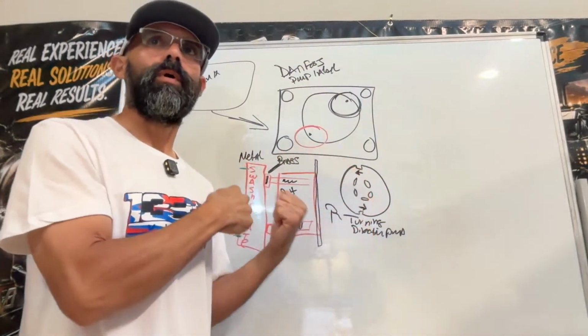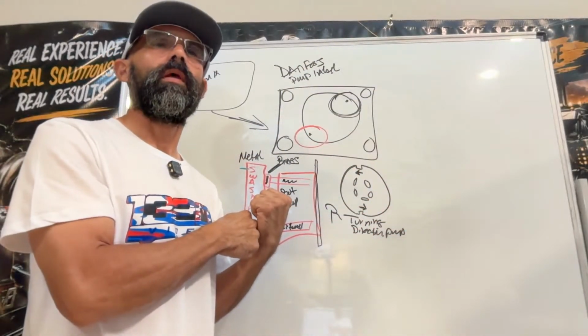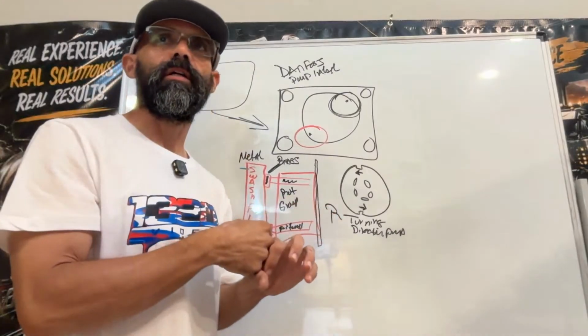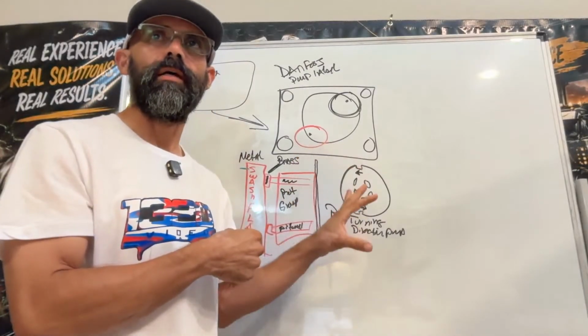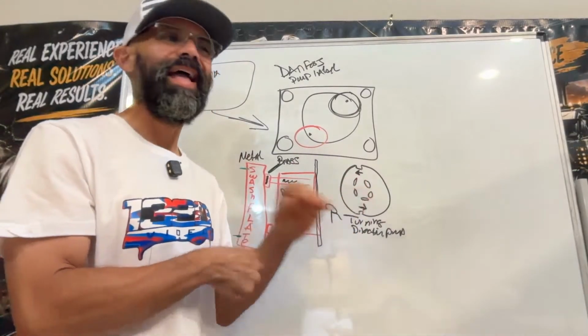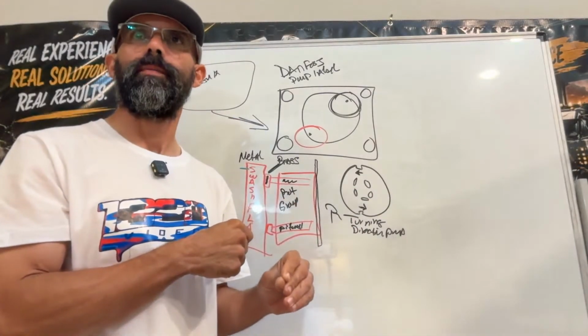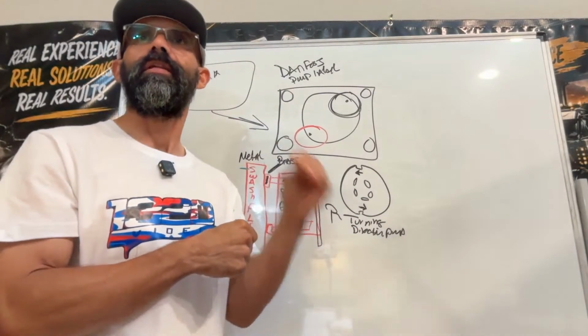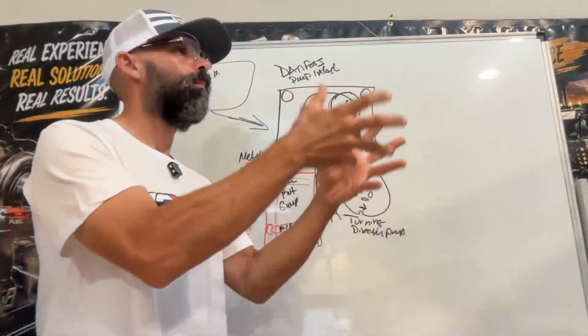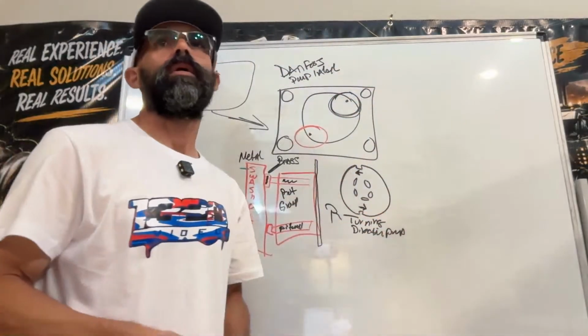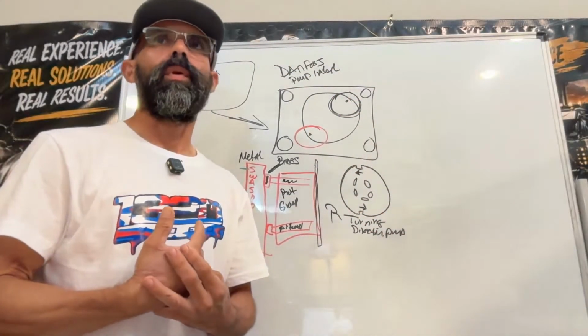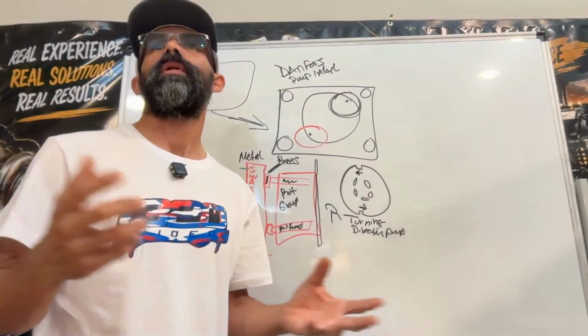I install the pump back into the equipment, I flush and clean every single hydraulic line, even the coolers. Everything needs to be cleaned out. Even the tank needs to be cleaned out. Everything, the strainers inside the tank, pull them out, clean them out. If they have to be replaced, they have to be replaced.